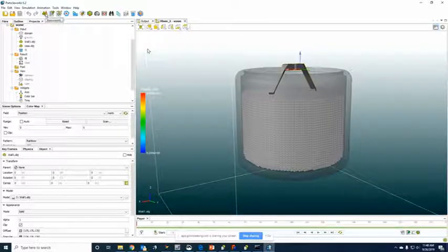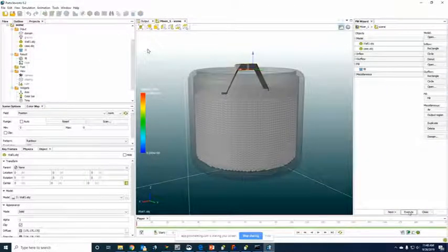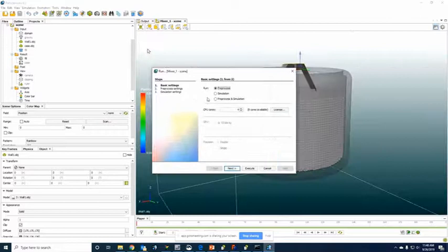Once your fluid properties are all set, you have to run through the pre-processing in Particleworks. In order to do that, you click this Execute, and select this pre-process and simulation. In this case, I'm using a Titan XP GPU that, for my setup, will run much faster than if I use the CPU cores. You can change between double and single precision.